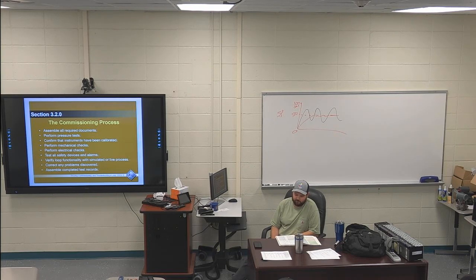They have the steps for a typical procedure. I've got step 3 highlighted. Verify that instruments have been calibrated. This is normally done by the instrument manufacturer, but may be required as part of the proving procedure. You can read through the rest of those steps, but I don't have anything else highlighted through step 9 or through the end of that section.